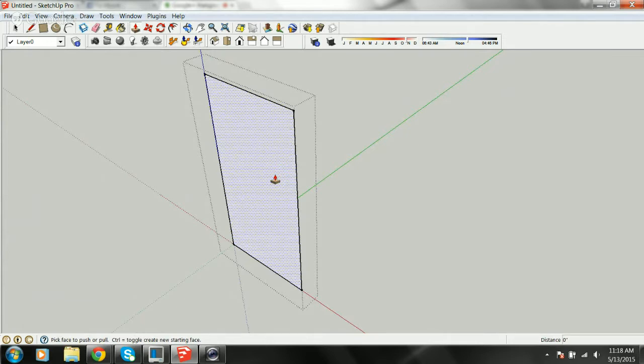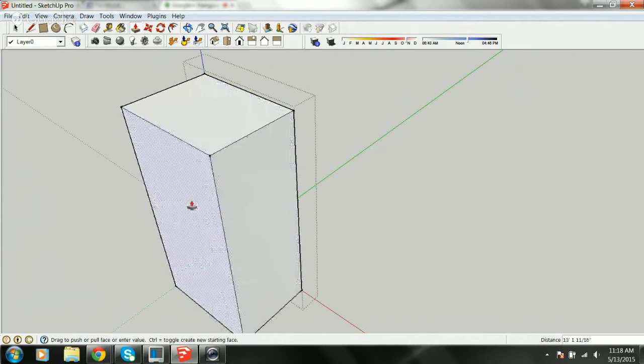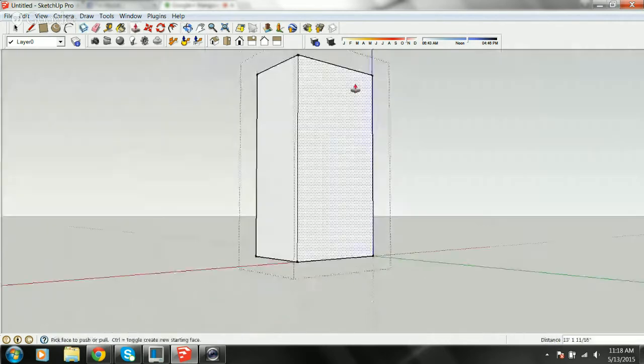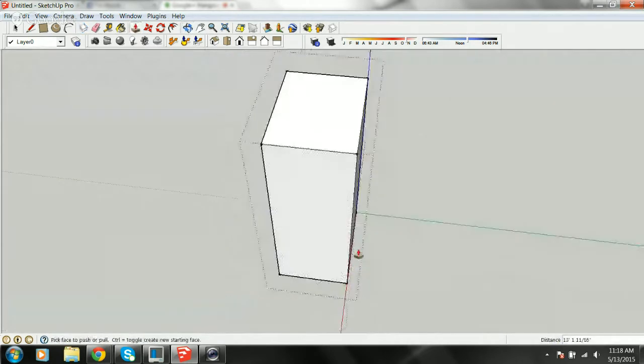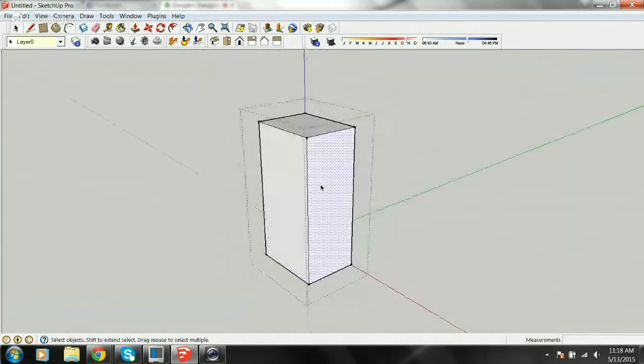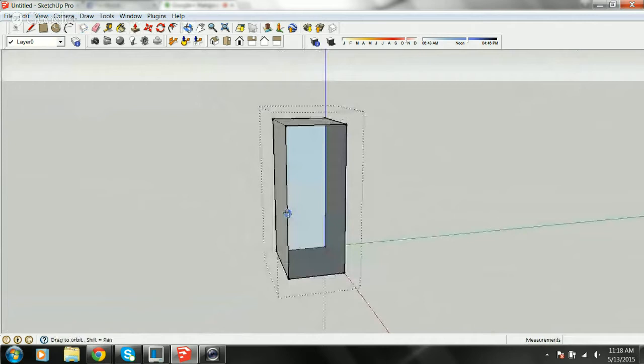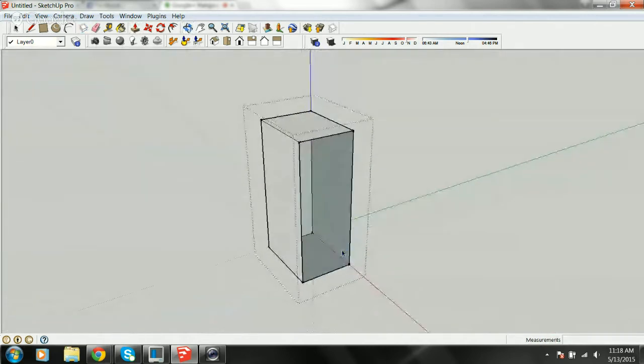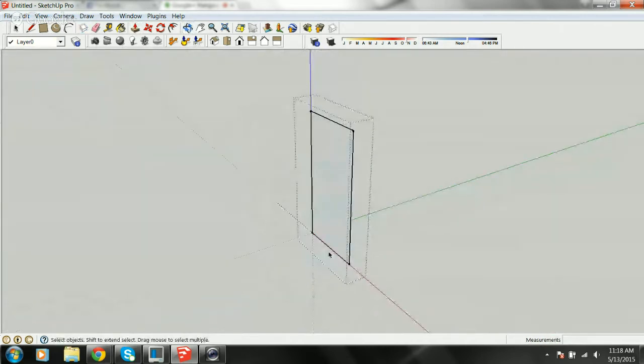Right. But the biggest tip I want to point out, well, here, I'll do this without hitting the control button, and I'm just going to extrude that out, okay? And as I start pushing and pulling this, it'll leave voids inside this box. This is a box of surfaces, not a solid. Okay, so if I click on that and I hit delete, you'll see it's void inside. Okay, so as SketchUp models, it's thinking in surfaces, not solids necessarily.